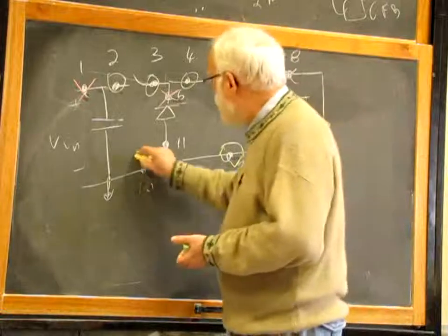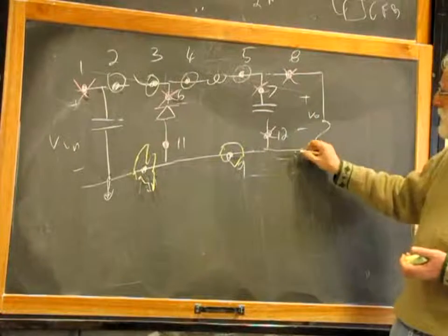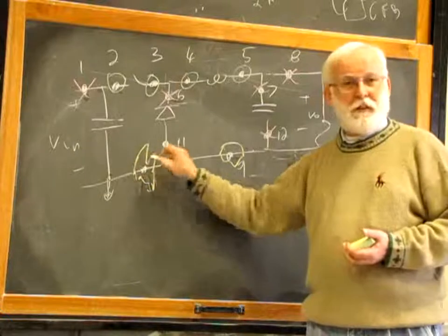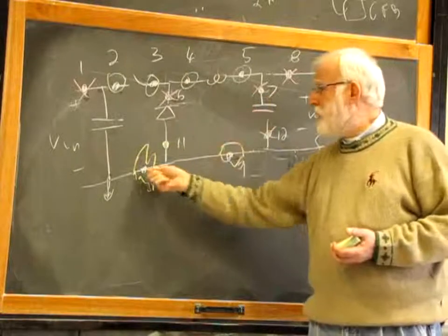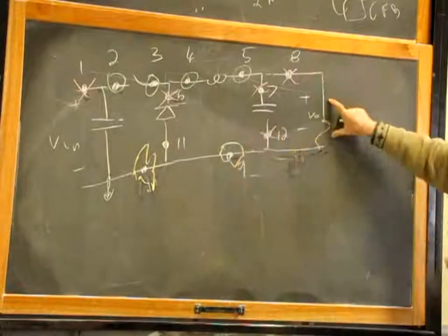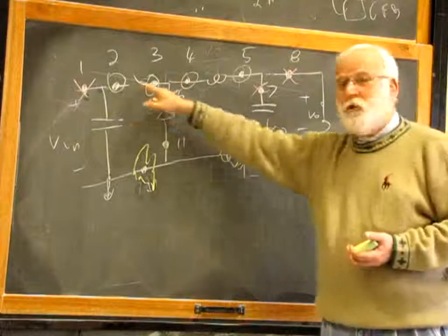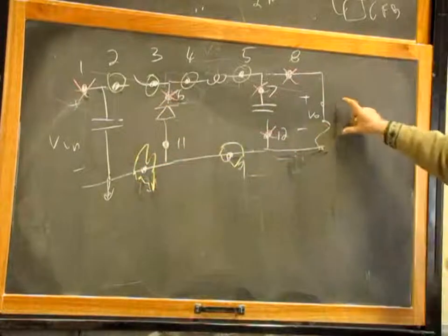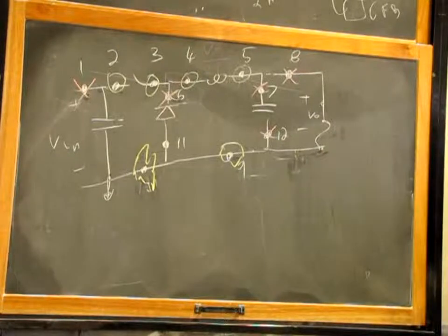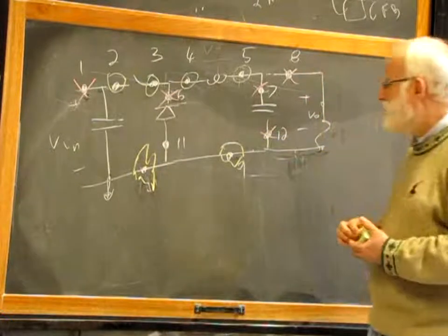And the same story is over here, but here is even worse, because even if you are smart enough not to connect to the ground at the output negative side, the voltage that is across here, because when you sense a current you generate a voltage for sure, is a pulsating voltage. So you have your output voltage, the common mode output voltage. Remember, we already discussed this when I tried to move the switch on the lower side. This will have a common mode voltage that goes up and down and could generate noise. Not too much, it's not as bad as placing just the switch on this side, but it's a bad situation.